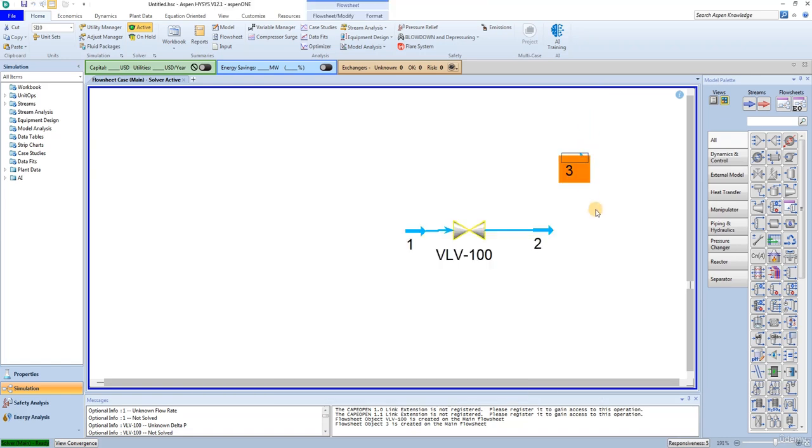The next block, the chiller, will be modeled in Aspen HYSYS using a heater operation. Since the heat lost by a theoretical process fluid would be recovered by the propane in the refrigeration loop, the heater operation allows us to represent the heat as energy flowing into the propane loop.